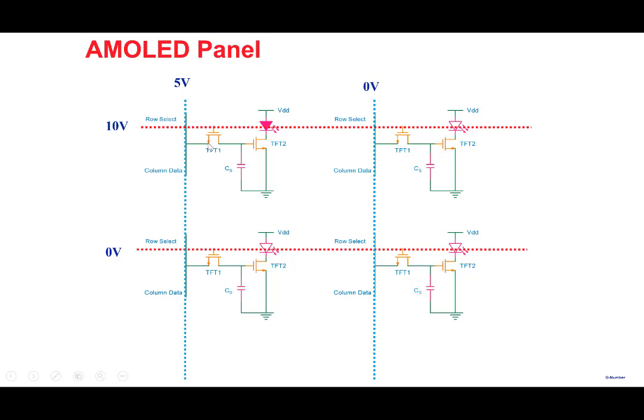The transistor, when it is on, has a certain amount of resistance. So there's an RC charging and the capacitor will charge up. And it will charge up to what? 5 volts, because we have applied 5 volts here. So it charges up to 5 volts.